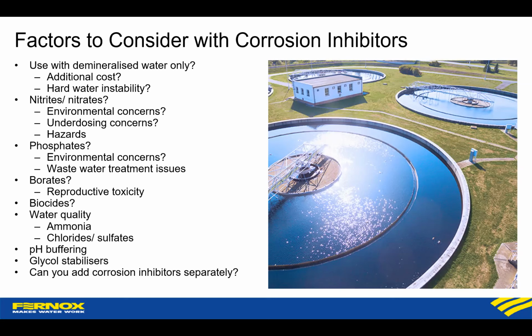You're not going to be thermally disinfecting anything, so you need to make sure that the heat transfer fluid you have is not going to sustain growth of microorganisms, which I'm sure you'll be aware cause a variety of problems, as I went through with corrosion debris on the previous slide, blockages, system failure, and you can also get MIC, which is microbial induced corrosion.